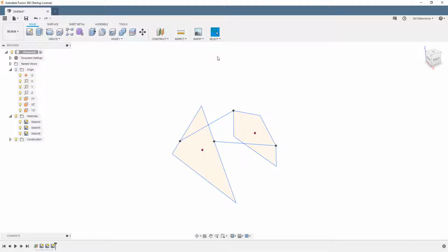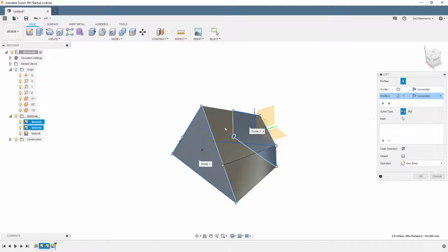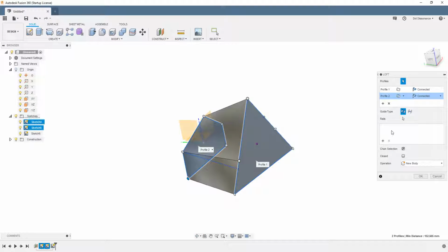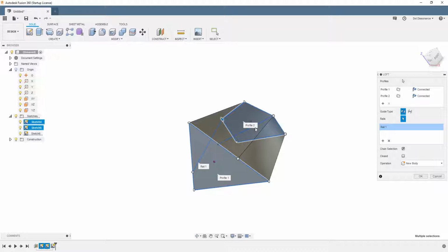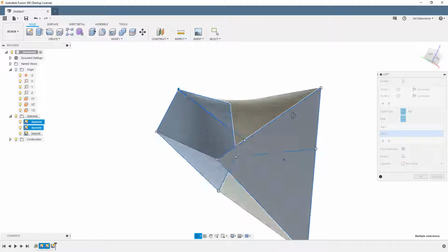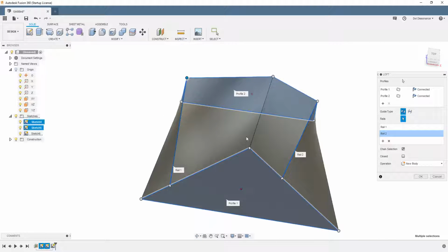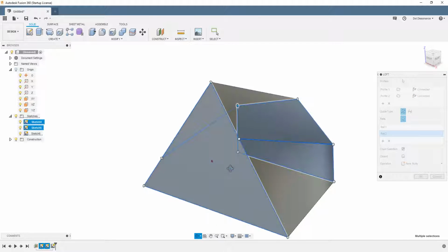So we'll stop the sketch, go to Loft, here to there, and now when you go to Rails, I can hit that, that'll line that one up, and then this one that's going right here, I say no, I want to use that one, and that lines that up. And then look around, like I said, look at all of your edges to make sure that they're singular and you're not seeing any other pieces in there.